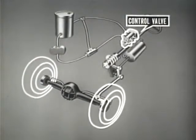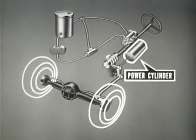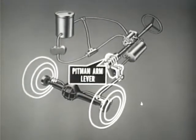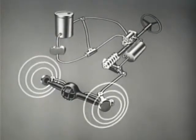The control valve directs fluid to the power cylinder. The power cylinder converts hydraulic pressure into mechanical force, which in turn actuates the pitman arm shaft and lever and the pitman arm, turning the front wheels of the vehicle through the steering linkage.